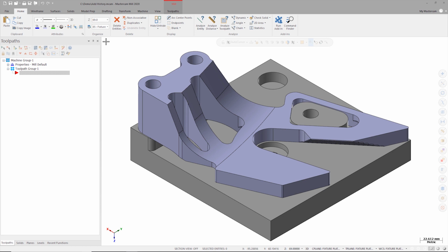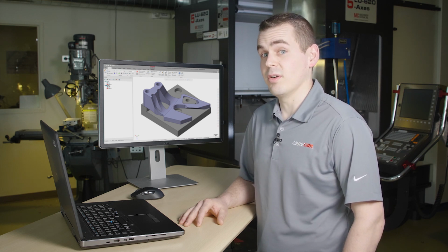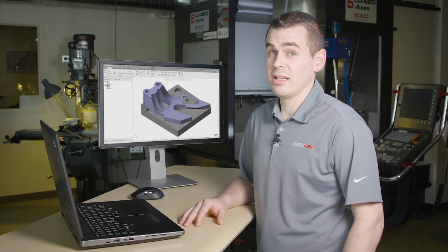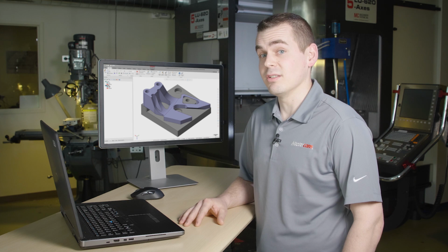It was created in a separate CAD system and then imported into Mastercam along with the fixture. When a solid is imported like this, it comes into Mastercam as a brick solid. What this means is that the solid body has no history, so all the features of the solid, such as holes, fillets, chamfers, or bosses, are not displayed in the Solids Manager as separate operations that can be adjusted as needed. If I had a complex solid that was modeled in Mastercam, and I used the Remove Solid History function, the solid would be converted into a brick, just like our imported solids. Now, I can use Add History to make features of a brick solid into editable operations in the Solids history tree.